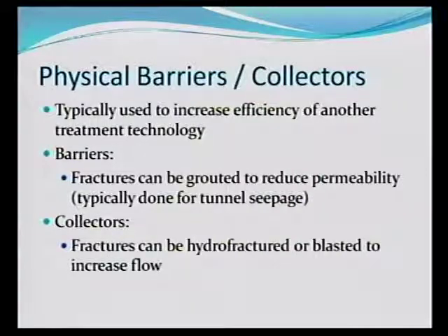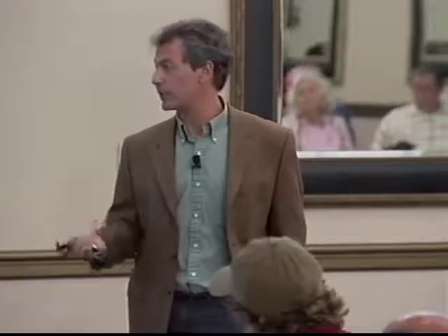Similarly, you can create collectors, or sort of like the closest we can get to a trench in bedrock. In shallow bedrock, you'll see what's known as blast trenches. So they drill a bunch of holes and they put explosives down there and they blow it up, and the rock just breaks up, right? So this creates a high permeability wall, and then as the groundwater moves and hits that wall, it'll flow to a central collector, and then that water can be pumped out. Okay, so it's sort of a barrier, not a barrier, but a perimeter that you can put around a contaminated area. But again, these are very hard to do on very large scales. This works best for shallow, focused areas.